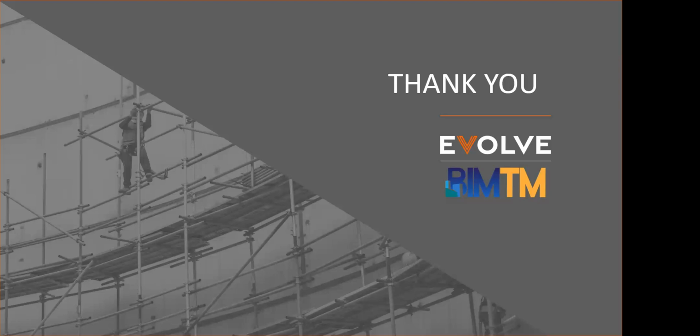So I do prefer fabrication parts over Revit families. Specifically, the reason is when you model with fabrication parts, you're getting true size parts and pieces. You're not getting imaginary models of duct that doesn't include insulation or doesn't have the flanges and stuff on it. So when you're getting into tight spaces and you're modeling in mechanical rooms and you're trying to avoid everything by a half inch, sometimes they're really tight, or even in between connectors, you can really dial that in with fabrication parts. And again, the best thing is you can just send it to your CNC and cut.